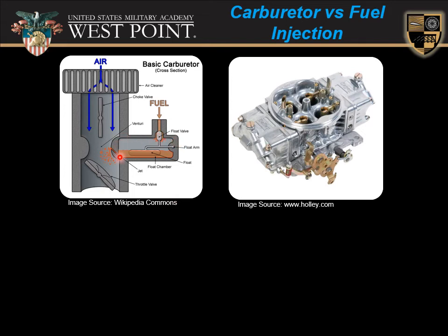Now, this float chamber doesn't contain all of your fuel, obviously. It just contains a small amount of fuel. And using the same buoyancy principles as the float in your toilet, as the fuel gets diminished or used within the float chamber, the float moves down. It opens the float valve, and that allows the fuel pump to pump more fuel into this float chamber.